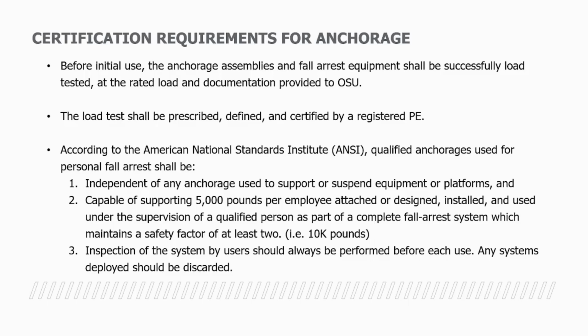According to the ANSI standard, the American National Standards Institute, qualified anchorages used for personal fall arrest shall be independent of any anchorage used to support or suspend equipment or platforms.